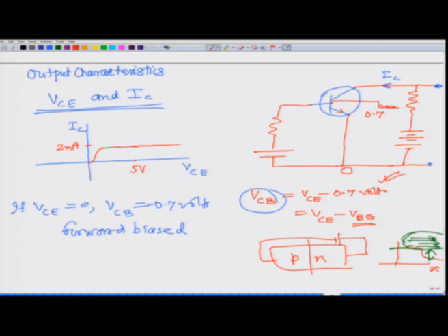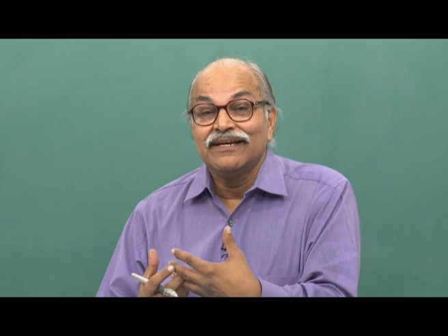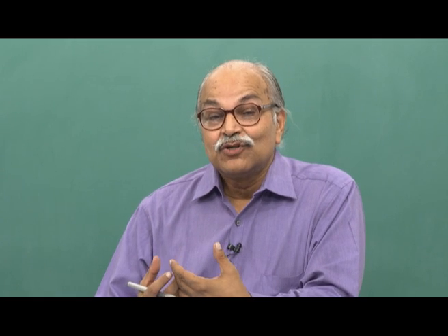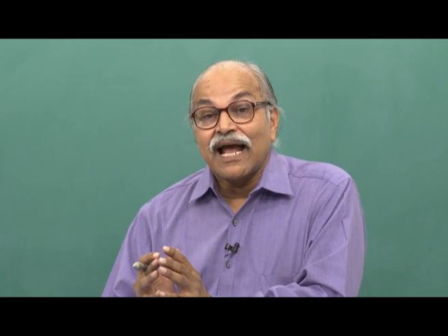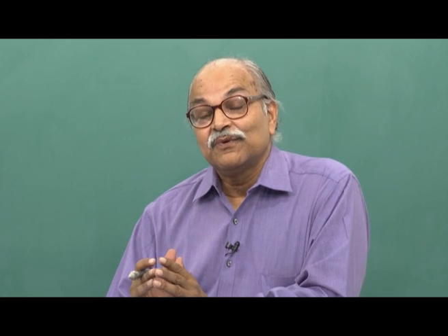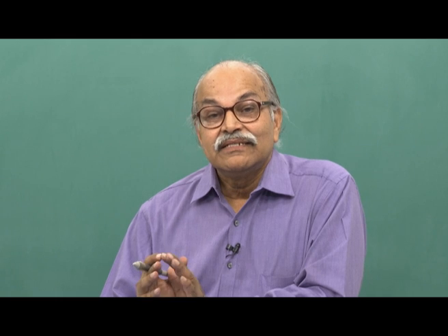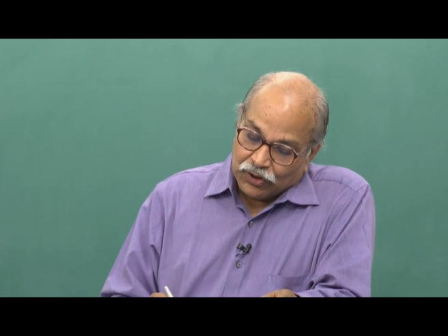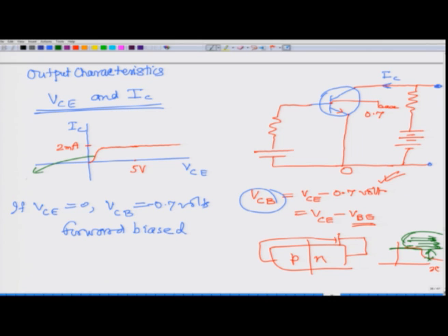The efficiency is saturated, it is no more drawing it, the reverse bias is not sufficient to draw the same fraction of these charge carriers it was designed for. So, that is known as saturation region. So, in this particular curve, this part will be called saturation region. What has saturated? The capability of the collector to draw that fraction of these charge carriers has saturated, and so this is known as saturation region.